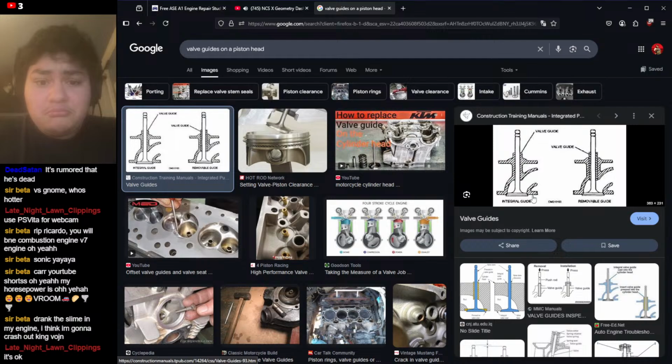That means you're burning up your engine oil. It means a valve is broken, or this valve guide is really messed up, or engine oil is just getting into your cylinder somehow. I don't know. Maybe a gnome dug a hole from the head straight into the pistons of the cylinder. But yeah, you want this to be snug.